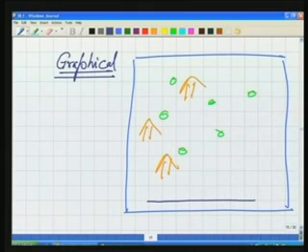What is the meaning of this? Here in our map, we make a line, and on this line we write, for example, 0, 100 meter, then 0 meter, again 100 meter, 200 meter and 300 meter. Further, we divide this first one into 10 parts. So, each of these is 10 meter.